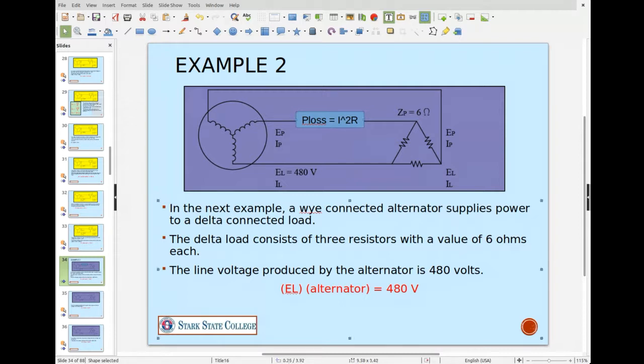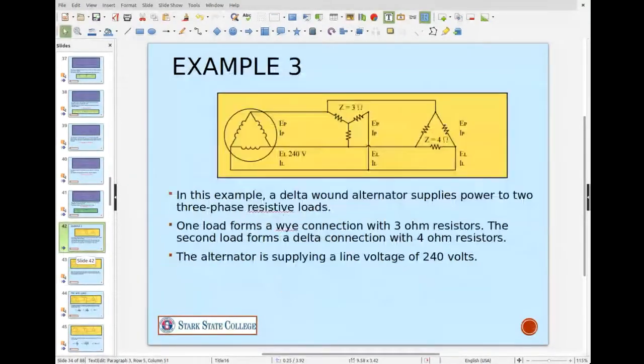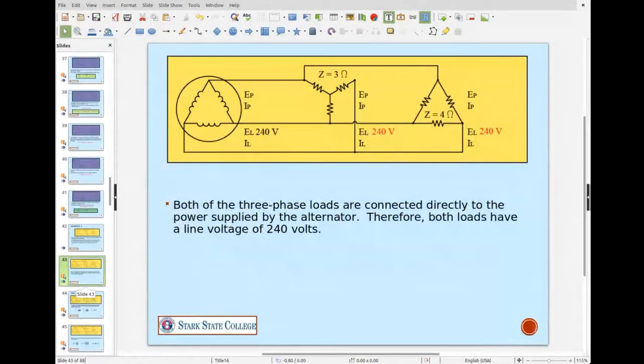Okay. And so, a lot of these voltages that we see, a lot of times we'll see like 480 volts for electric motors and other big loads. Okay. And if that's not big enough, then they tend to make them even larger. So you see some of the motors run at like 1,000 volts or something. So you can reduce your current, but still get the same power. And you also reduce your loss in there.